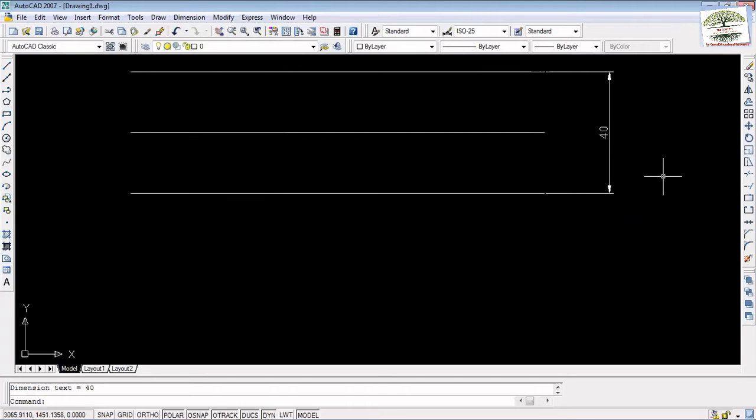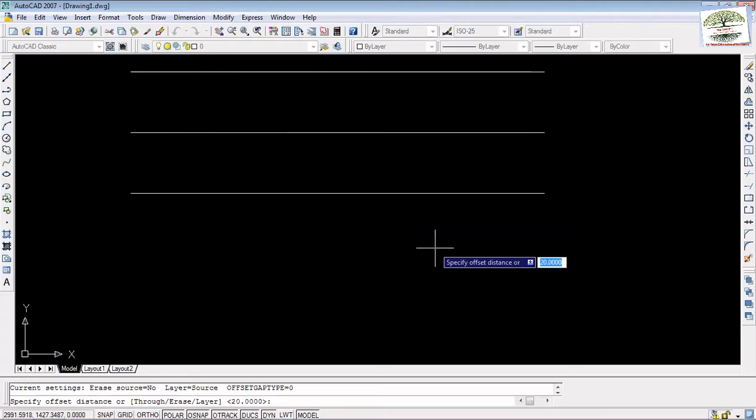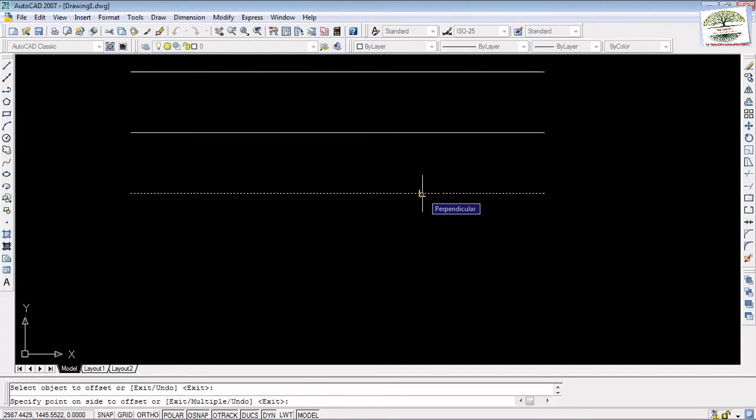So you can go for it, select an offset. This is the final one, I'll not tell any more. This is left click on the offset. Distance you have to make, 15 I'm giving this time. Spacebar or enter, anything. Last time I showed you by giving input using spacebar. Now it is enter. Left click on the object which you would like to offset. Now select the direction in which you would like to offset. Whenever you are selecting the direction, there is no question of any right click. You have to go only with the left click. No right click.